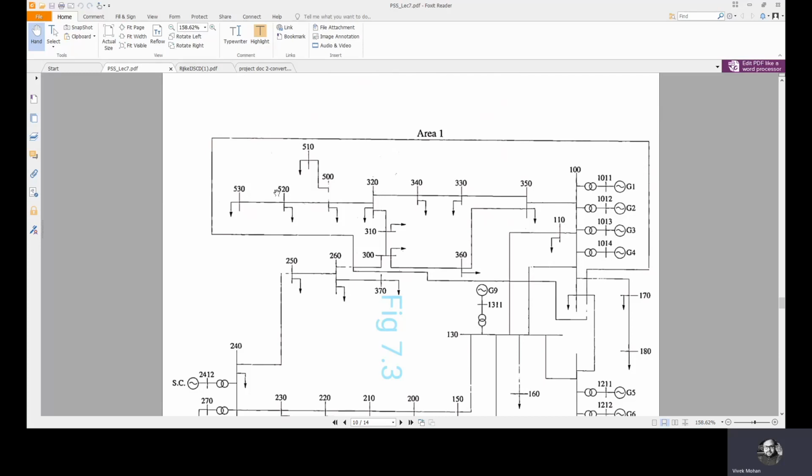So at each step we are executing a load flow so that we get all the output variable values. That means V530, V520, V510, V500. These are the voltages at buses 530, 520, 510, 500, etc. We want P, Q, V and del for all these buses.